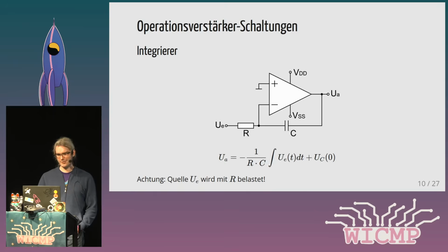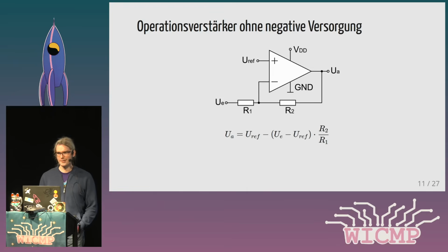What else do we need? So we only have 5 volt and ground, and this is what we see. We don't have negative extra voltage. What do we do here? We connect ground. We have VDD with 5 volts at the very top. And this is an inverting amplifier.